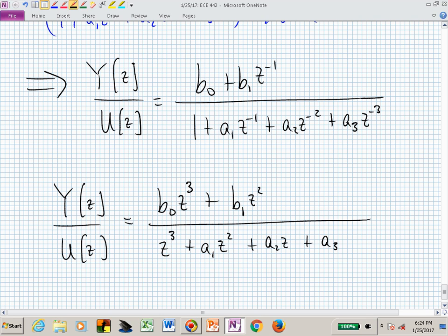And if I gave you a's and b's, you could find the roots of the numerator, which would be zeros of the transfer function, or you could find roots of the denominator, which would be poles of your transfer function. And you could put those as x's and o's, poles and zeros in your z-plane. How many poles do you have in this particular system? What's the order of your denominator polynomial? 3. I apologize for those that are listening. You didn't see me scratching with 3 fingers. Luckily, it's third order, right?